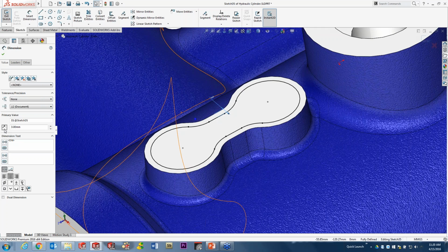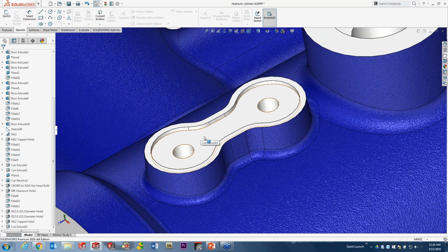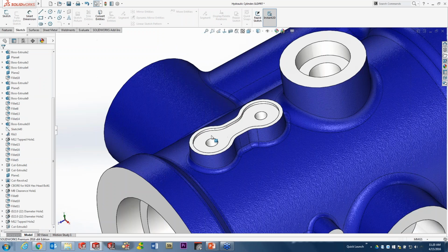That will take the sketch offset and flip it to the opposite side, and now if I go ahead and exit this particular feature, that's going to give me more of a spot face in there as opposed to more of a grinding operation that it did before. But the point here is that when you offset entities from an edge of a face, you have the ability to edit and reverse those instead of deleting and redoing.